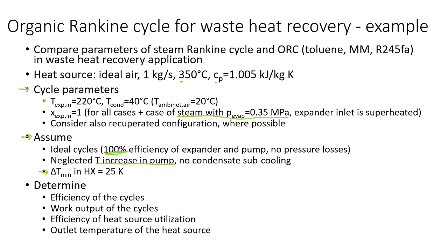And the task is to determine the efficiency of the cycles, both simple and, eventually, if possible, recuperated. Then the absolute work output of the cycle in the units of kilowatts. Not just unit work in kilowatts per kilogram of working fluid, but also we will calculate, for the given heat source parameters, the absolute power that we can get out of it.